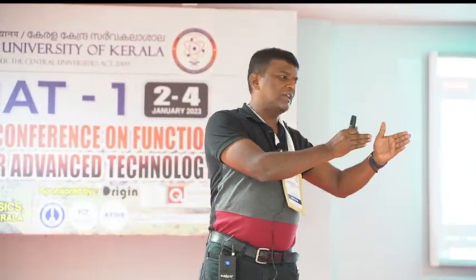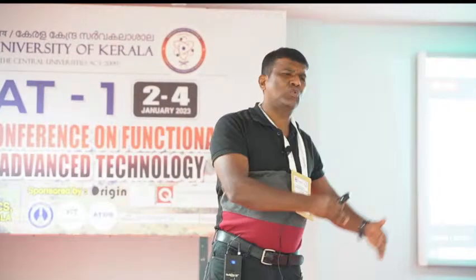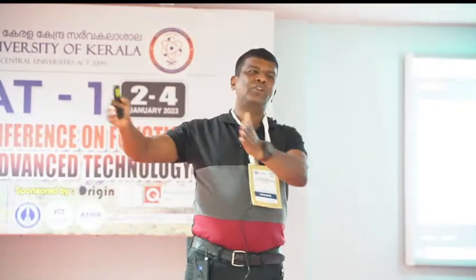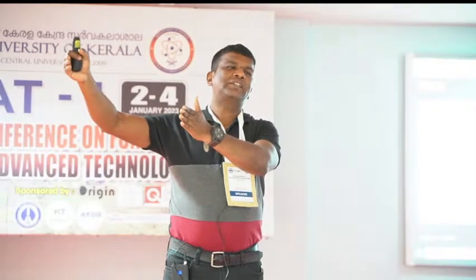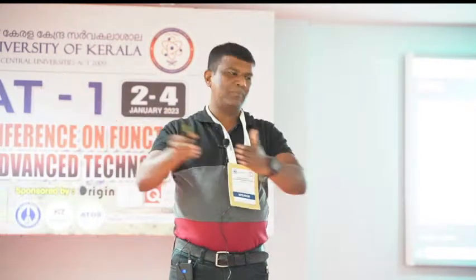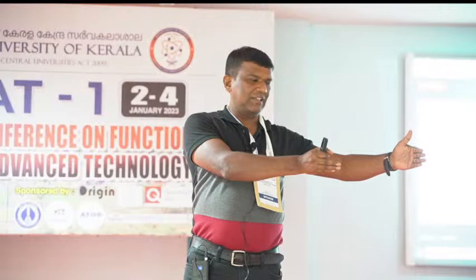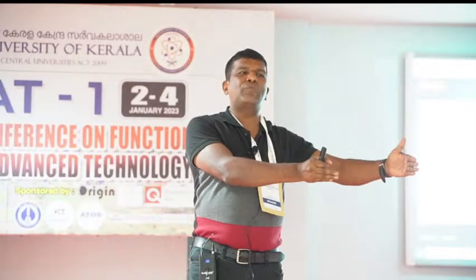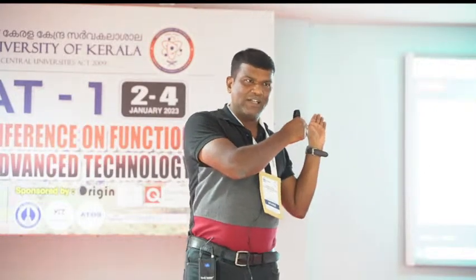You are performing signals in the range of 10 to 20 to 30 kilohertz, whereas your resonant peak is around 150, 160 kilohertz. So far away from resonant frequency, you are imaging, right? So this is all called off-resonance PFM measurements, what you are doing at this moment.